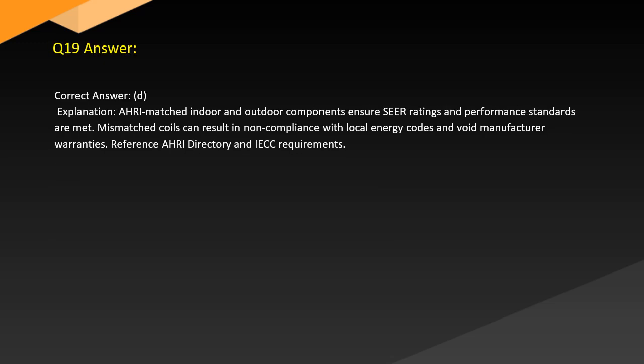Answer. Correct answer: D. Explanation. AHRI matched indoor and outdoor components ensure SEER ratings and performance standards are met. Mismatched coils can result in non-compliance with local energy codes and void manufacturer warranties. Reference the AHRI directory and IECC requirements.